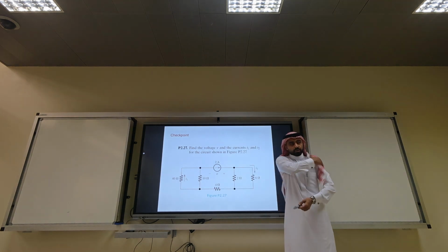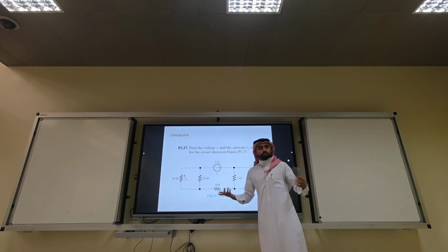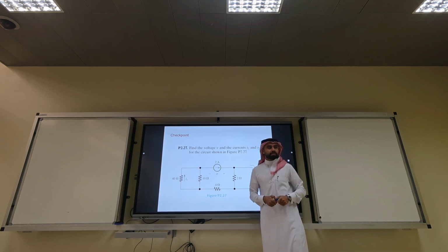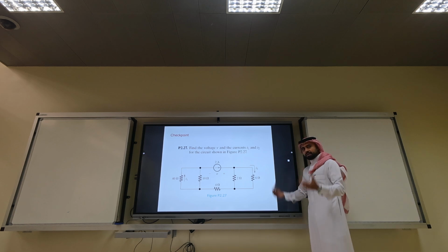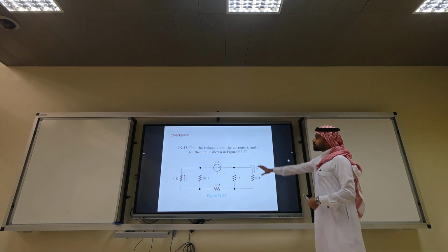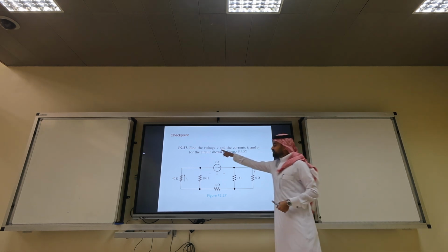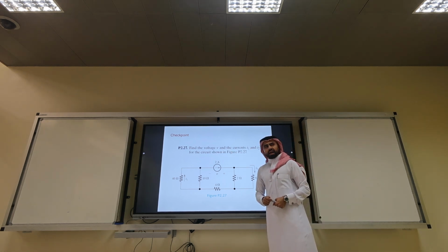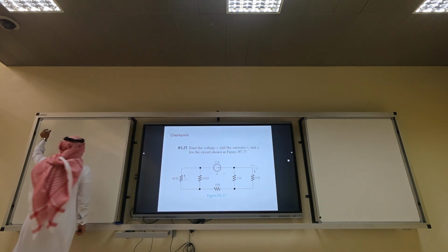So if I bring a question in quiz 2, and we reverse the directions, you will be able to answer it, and then you're not going to complain about the time, right? Because part of the testing is the time. So how to solve this equation? Which one is easier? Can we find I1 and I2 before the V? Yeah. We're going to use CDR, current divider rule, right?